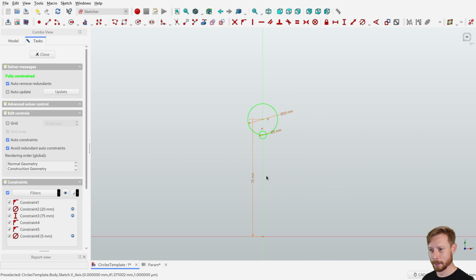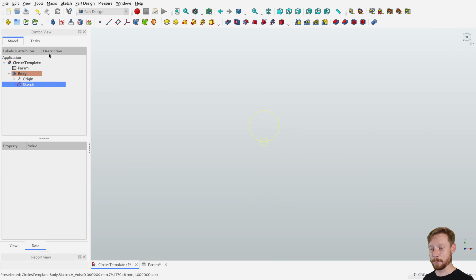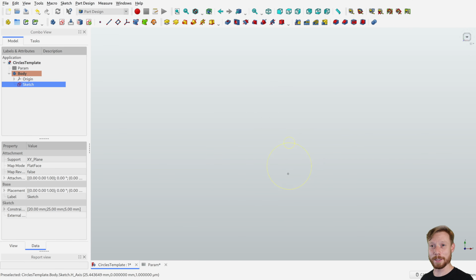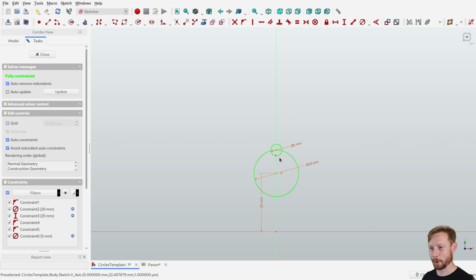Everything's correct. This must just be one of those FreeCAD things. It's still fully constrained. Why does FreeCAD do stuff like this to me? Well, it's done everything that I said to. So it's still attached to that center X line. It's still attached to the outside of that circle. The issue is the order that the sketch solver will solve things and the order that I put constraints in and so on. So it's best to just follow my second rule, which is use absolute references wherever possible.